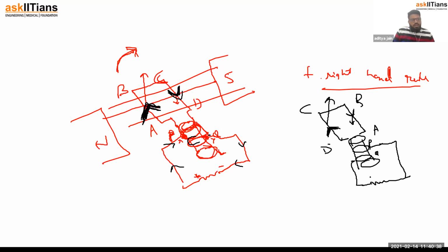Yes, this is the situation. This is the resistance. I have drawn the external resistance. So if you carefully observe now, the direction of current in the external circuit will be like this. Why am I saying this? Because this is Q, this is P. They have changed their position with the brushes. So that's why the direction of current is being reversed.